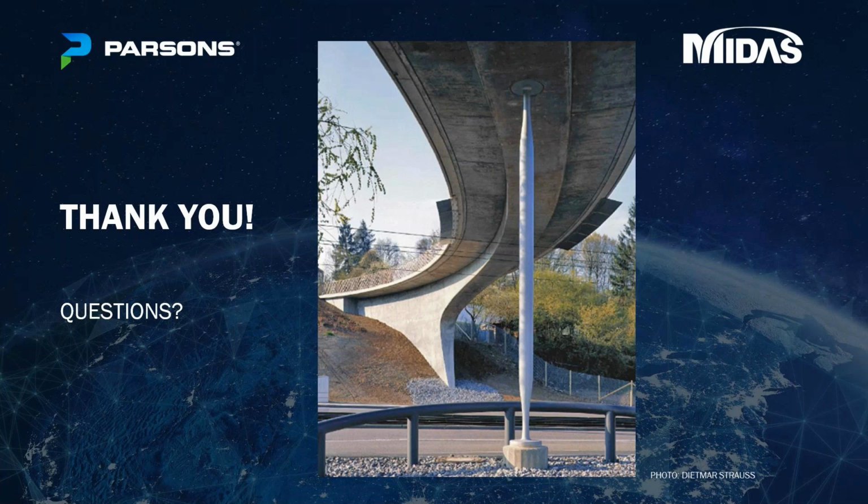Okay, the next question asks, what is the maximum single span integral bridge that has been built or can be designed? Good question. I think the maximum span for an integral bridge depends on the moments for vertical loads, because the larger the span gets, obviously, the more heavy-duty the superstructure gets. But when you think about cable-supported bridges, suspension bridges, and so on, Jörg Schleich showed through various pedestrian bridges that you can actually build very long spans with cable-supported structures as long as you take care of the restraining effects. He does this in a way that the monolithically connected superstructure to the abutments stabilizes the superstructure, so that you, for example, may need only one cable plane to support the superstructure when you have the torsional stiffness.